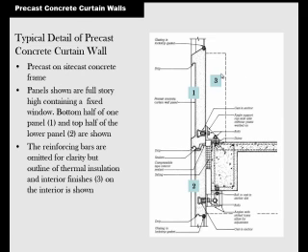This one is, you got a concrete structure there. You've got your angle that will hold this piece of precast concrete. Then you have your labyrinth. Remember we were talking about that. The drip edge, the sealant. There's some interior sealant there. So that's another good detail to copy and study.